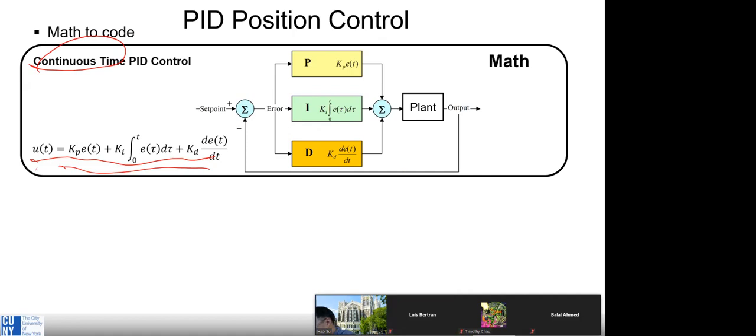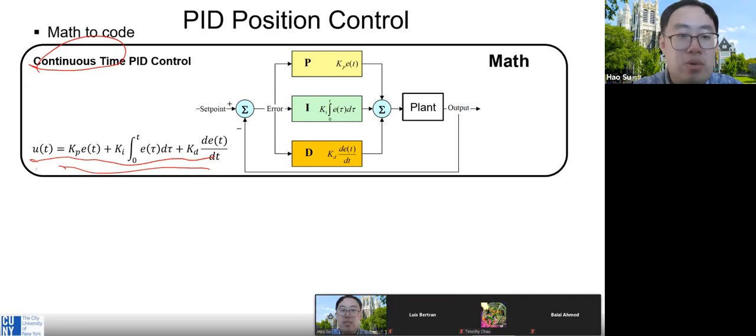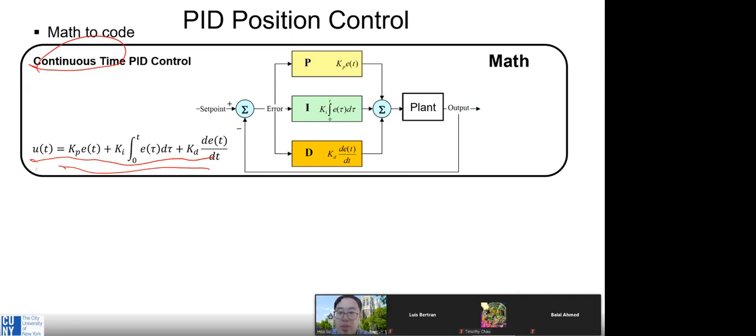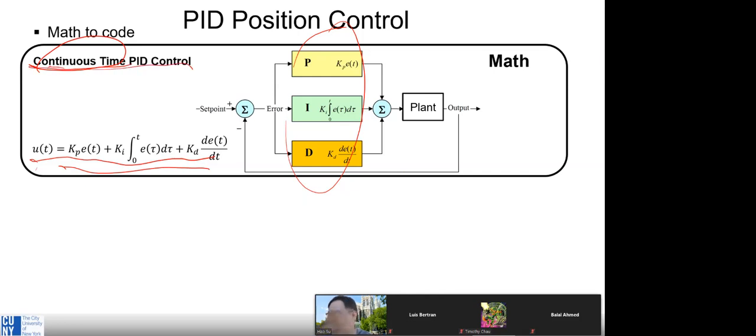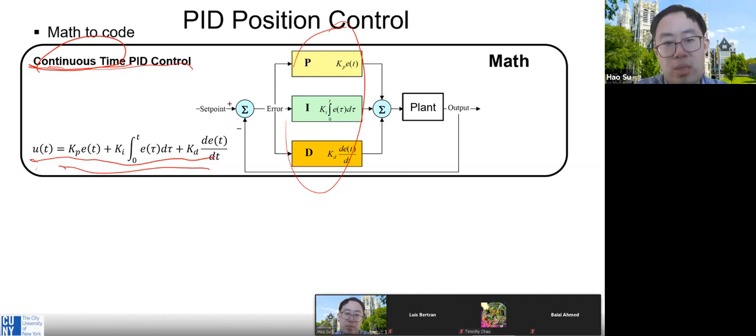You can use Simulink, and Simulink can connect to the Arduino. Okay, that's one solution. But if we think about Arduino itself, how can we do everything in Arduino? Let's say you want to do the PID controller inside Arduino. This is a continuous time domain, an ideal mass model. But if you need to implement it in the hardware, what's the major difference? Do you realize the difference?